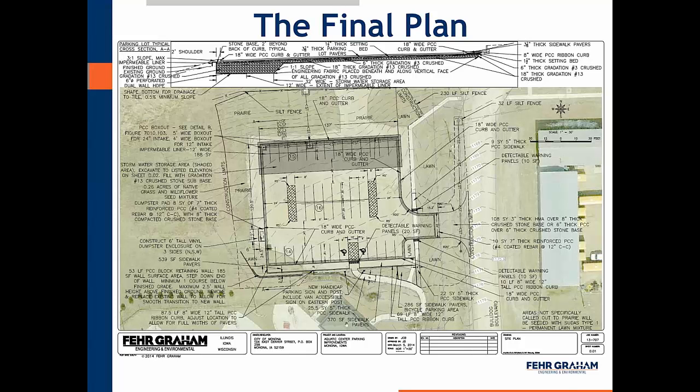Knowing that we had very little infiltration from native soils, we designed a tile under drain through that reservoir. We have it just off the surface, 6 or 8 inches. And then that is tied to an outfall line that you can see goes off the upper end and ties into the storm drain system. That's to provide a slow, managed, controlled discharge versus just allowing it all to run off at a high rate.